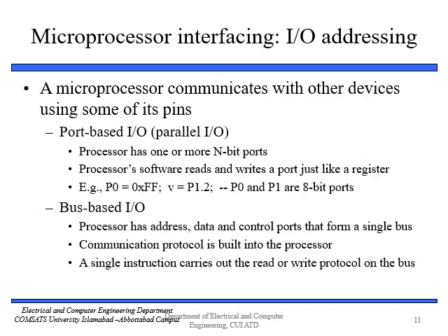In this slide we are going to talk about microprocessor interfacing, that is I/O addressing, input-output addressing. A microprocessor may have tens or hundreds of pins, many of which are control pins, such as a pin for clock input and another pin for resetting the microprocessor. Many of the other pins are used to communicate data to and from the microprocessor, which we call processor IOs.